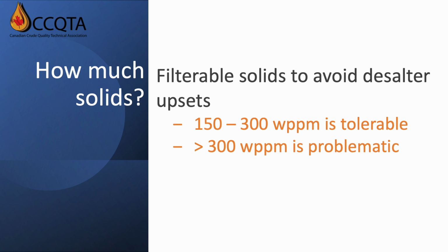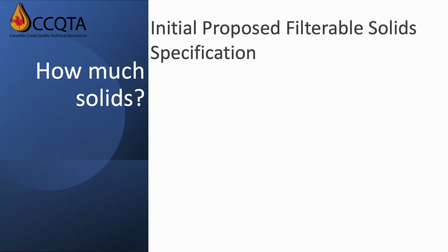Note that some refiners did comment based on their experience that 300 weight ppm is too high for their plant. Regardless, the average daily filterable solids content of 200 weight ppm, calculated from the historical data, appears to be in the tolerable range.